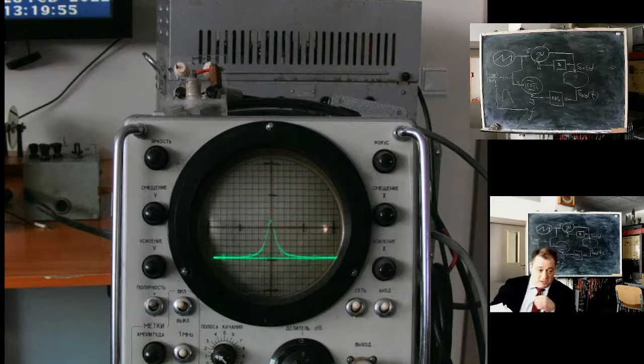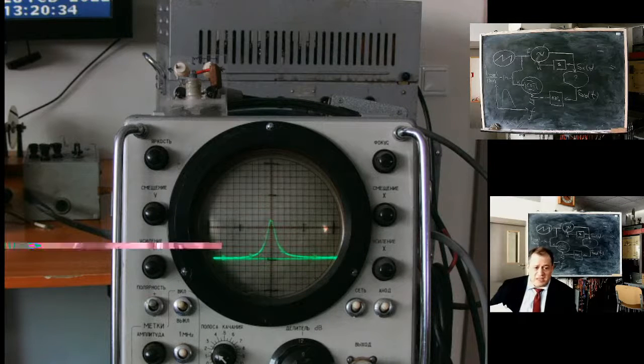So at high frequency, when somebody is fool enough to touch live parts, current gets into his body. But this current flows at the skin surface, under the surface but very near to the surface, where there are no nervous connections to the muscles. So you don't get a shock, but current flows and burns. Thermal effects remain. So don't touch live parts in any way.